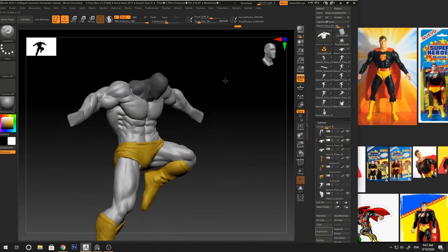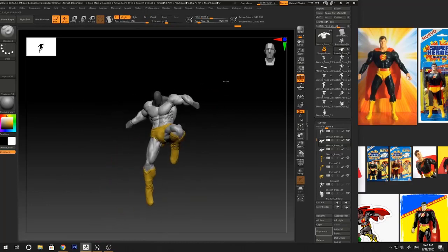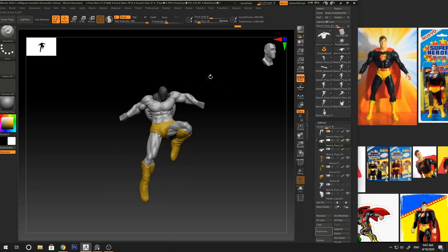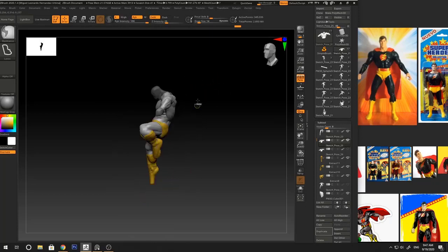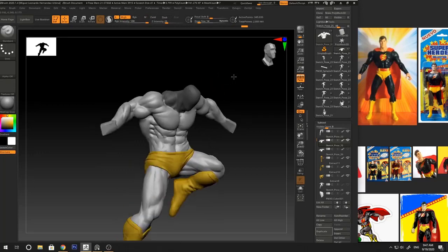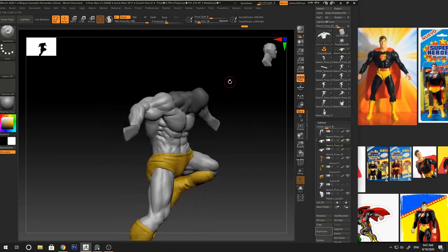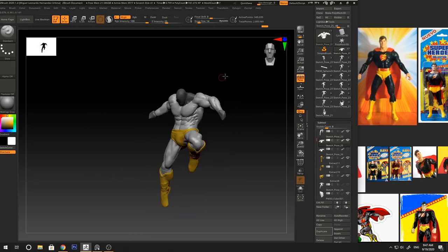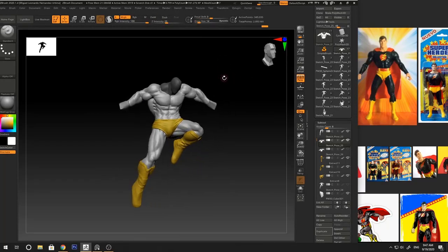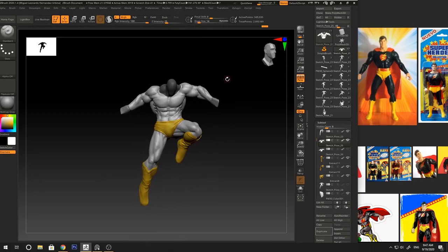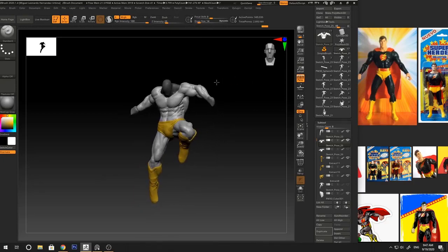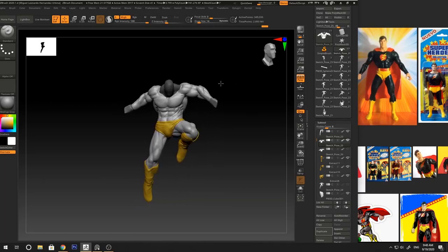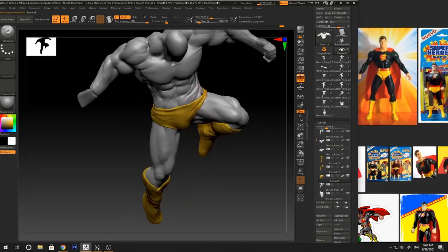these collectible pieces. Sometimes you will receive the whole body, but sometimes you will receive the half body and the legs and the head separately. So you need to create these pegs and keys and holes to make this thing work. So sometimes it's important in the design process, you have to cut, you will have to remove the head, or maybe you have to produce the torso separately from the legs. So it's important to have lines that hide that cut.